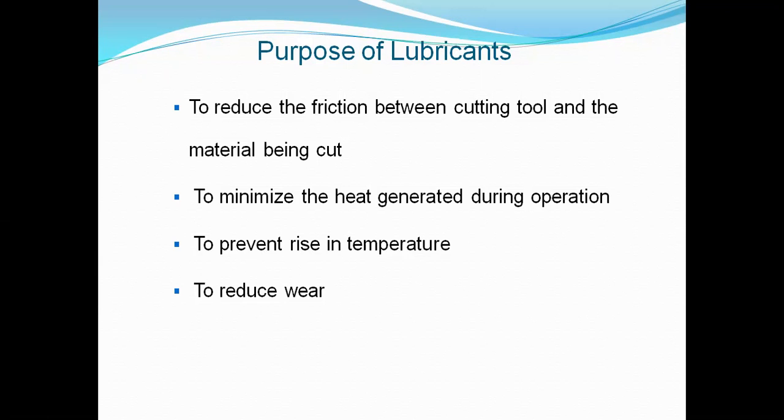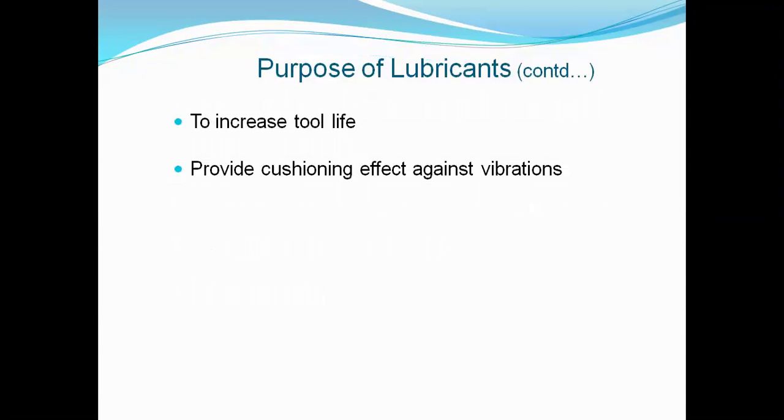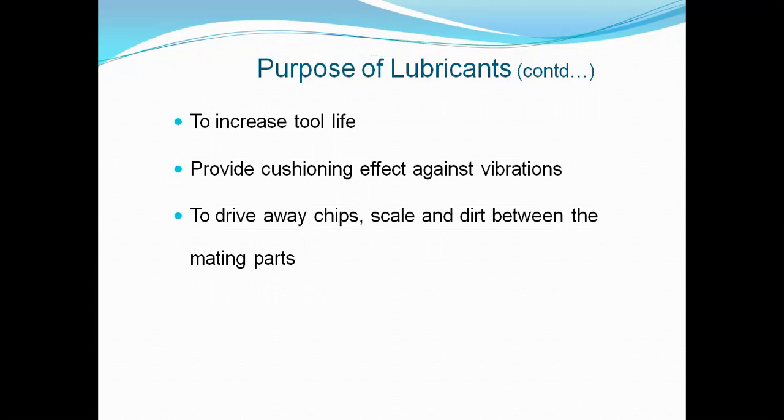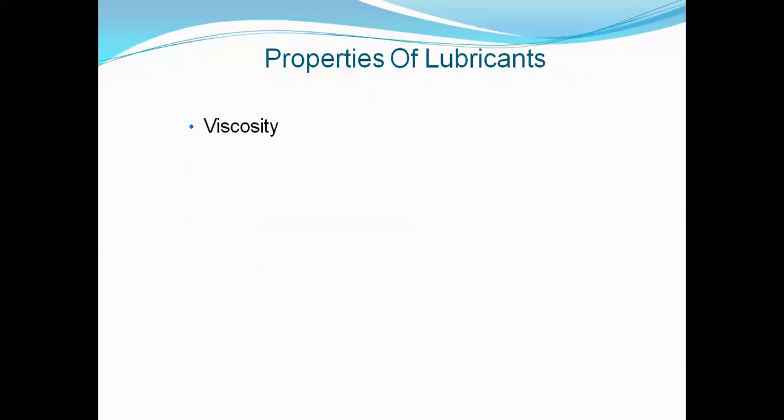If the friction is reduced, automatically heat generation also reduces. And if the heat generation is less, the rise in temperature is also less. And wear also reduces, and tool life increases. Lubricants also provide a cushioning effect against vibrations, drive away chips, scale, and dirt between the mating parts, and protect the finished surfaces from corrosion.